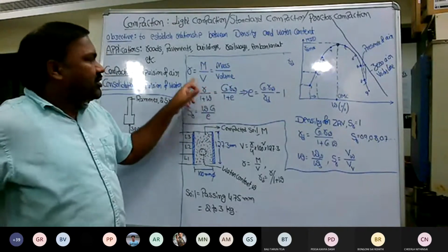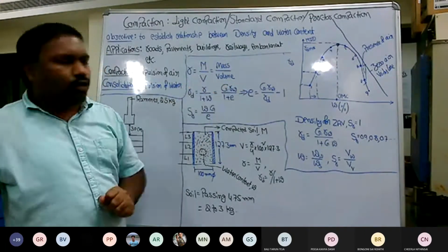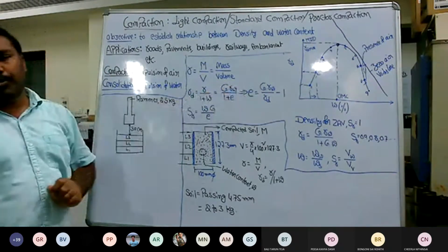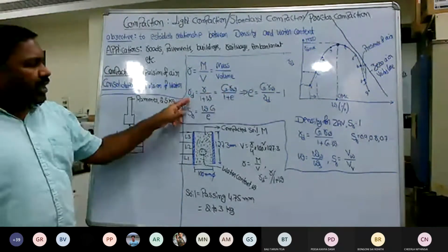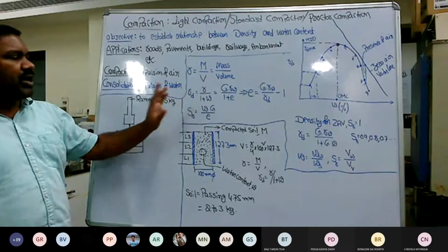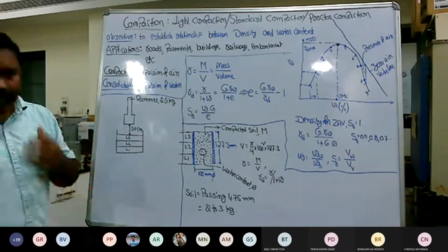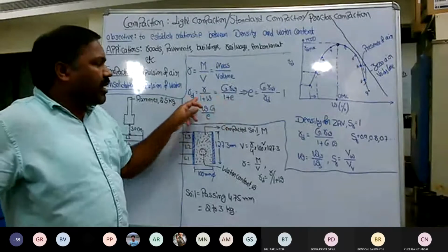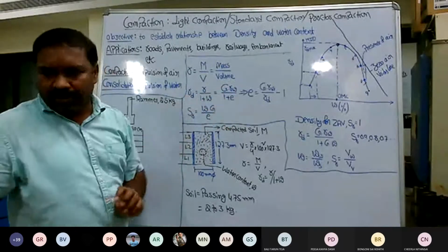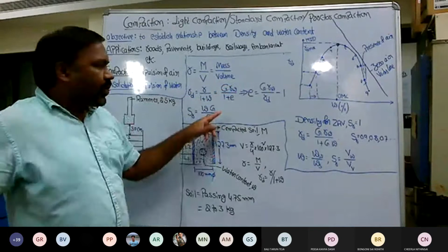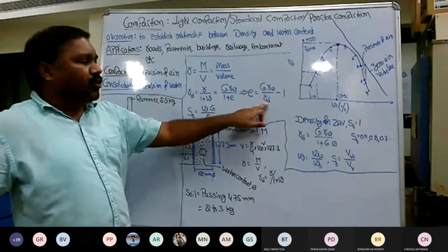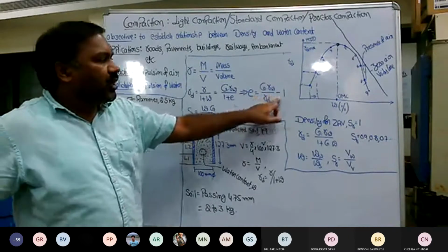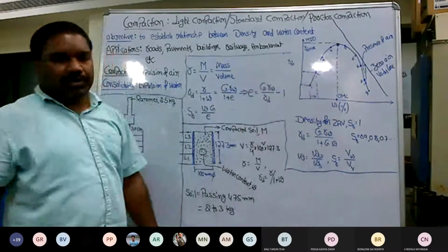Now, if you write the same equation for gamma, you may have to include the degree of saturation additionally in the numerator. But when you deal with the dry density, we assume that it is not fully saturated. Therefore we assume Sr is 0. So then we arrive at gamma D is equal to G into gamma W by 1 plus e. From this relationship we can back calculate, for the known dry density, what void ratio you are accomplishing at particular density values.